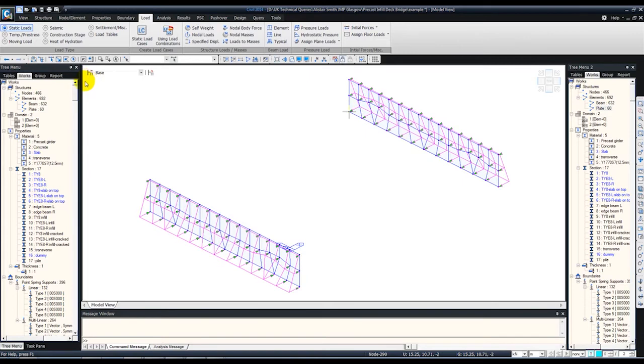So let's see how to do that. For the construction, when we place the precast beams, we assume that they are simply supported, and then when we cast the deck, the entire thing becomes composite, including the integral abutments and everything. So let's give some moment releases to our precast girders, the TY beams.